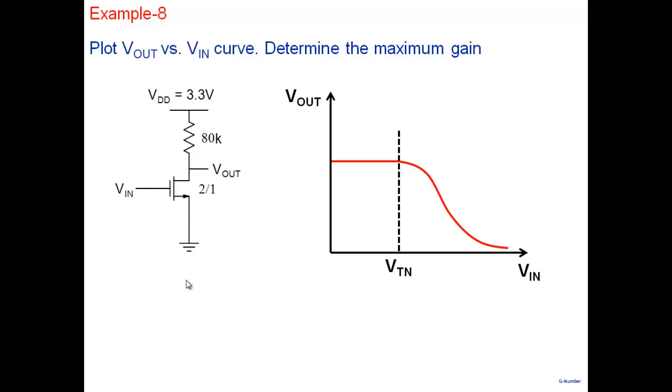So note that just above threshold voltage, current is still going to be small. So what will be the value of this voltage? Close to 3.3. And what is the saturation voltage required if I apply 1.1? 0.1, and the voltage here is 3 or so. So obviously it goes into saturation region. So immediately once you cross this, it goes into saturation region, right?